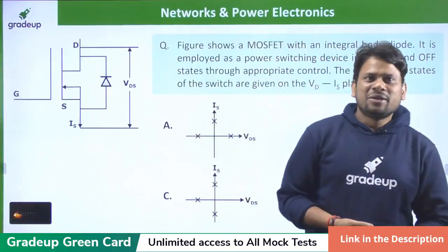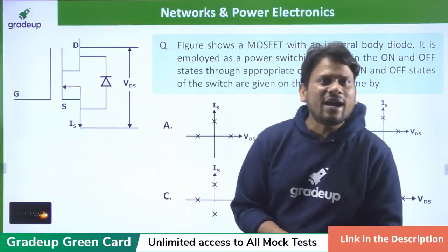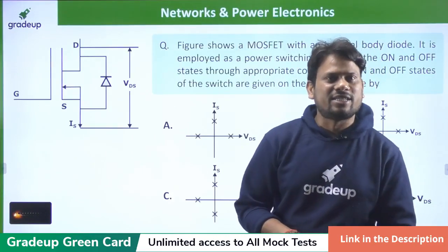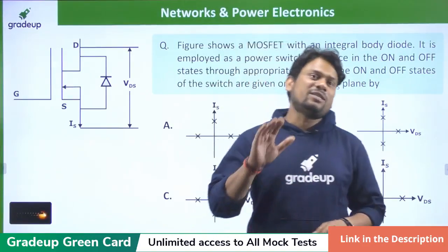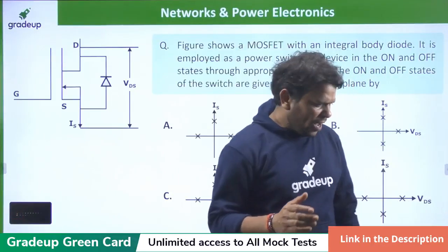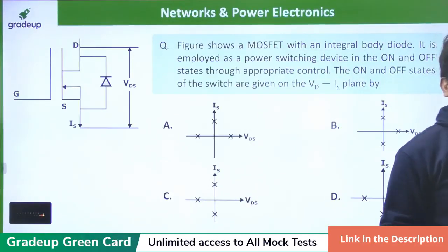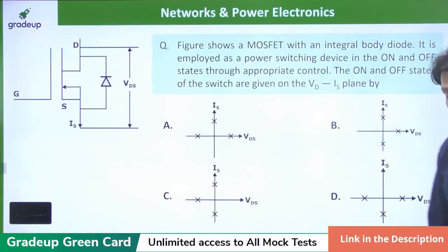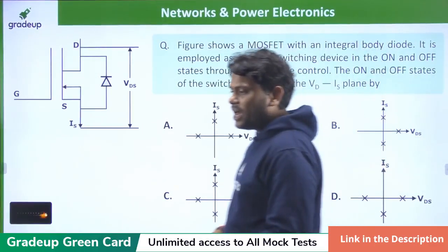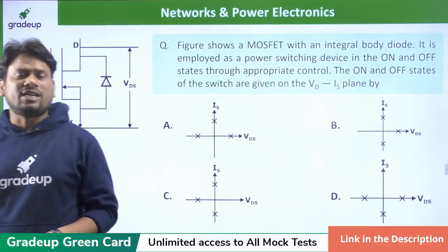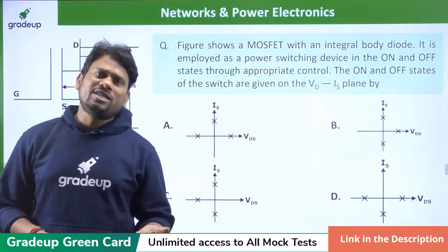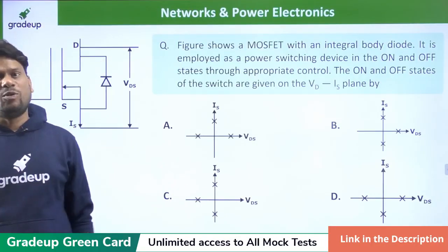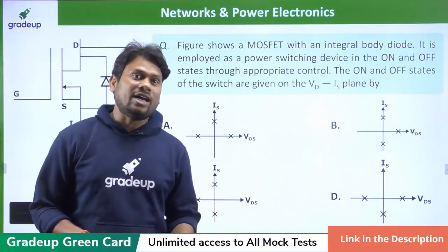Now, it acts similar to SCR characteristics. Yeah, Kumdini, it will be similar to SCR characteristics. Why will it be similar to SCR characteristics? Because SCR can block voltage of either polarity and can pass current in a single direction. But everyone, there is a lot of difference between SCR and a diode and BJT series connection. A diode and BJT series connection cannot sustain high voltage, but SCR can sustain high voltage.